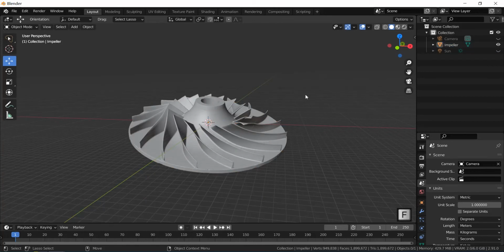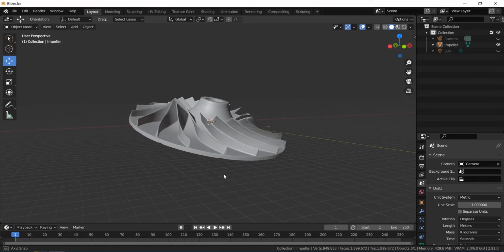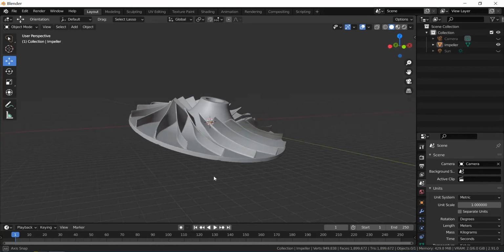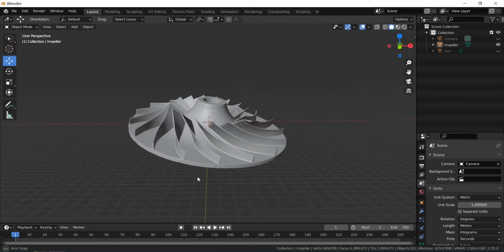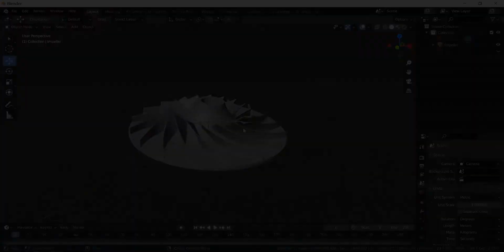This is because when the scanned model is imported into Blender, Blender by default places the origin of the scanned model at the center of the Blender world coordinate system. So we need to move the theoretical geometric center of the scanned model to that origin. The scanned model is now placed at the world coordinate center of Blender.